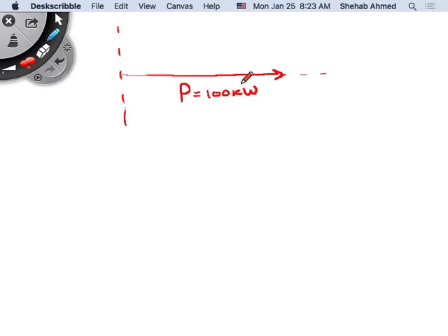So where can I draw S? On top or on the bottom? On top. So it's 0.8 power factor. How do I find the angle theta, the power factor angle? So cosine theta, or cosine phi, whatever you want to call it, is equal to 0.8, right? This is the power factor. So you take the inverse cosine of 0.8, what is that? Okay, so we know that at some angle here, 36 point something, theta, which is the inverse cosine of 0.8, we can draw it. I didn't draw it nicely, actually.